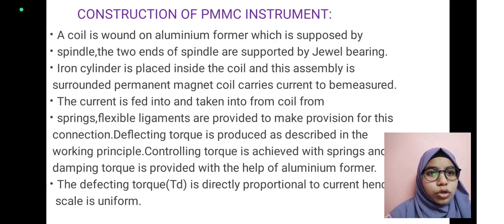And deflecting torque is produced as described in the working principle. Controlling torque is achieved with springs and damping torque is provided with the help of the aluminium former. The deflecting torque, that is TD, is directly proportional to current, hence the scale is uniform.